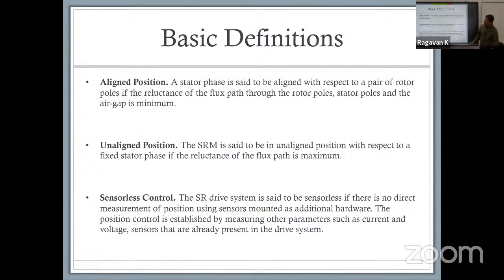In which you're basically creating motion. Now, as you're doing something like that and you have unaligned position, you are basically creating the concept of an electromagnet which is attracting a piece of metal. What that means is that whenever the rotor is trying to get aligned, if you are not careful, you can end up in a situation where your rotor comes to a sudden stop. It would be very similar to when you are driving. If you don't recognize the stop sign, or if you don't know where your stop sign is and you don't apply your brakes until you have to stop, you will get that massive forward motion. The same thing happens for the motor as well. So there is a need for awareness to recognize when the phase needs to be de-energized and what that dynamic setup is going to be.